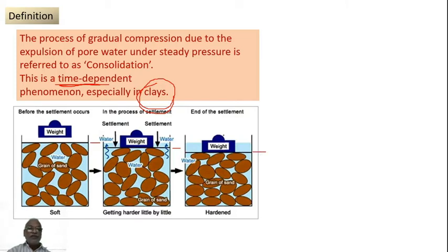So as long as there is some kind of pressure developed inside this pore water, it tries to go out, and then if that pressure is reduced to zero, there is no question of water going out. Now as you see here, when you put the load, there is pressure which is developed inside the water, it is trying to go out. By the time it comes up to this level, there is no pressure left inside the water. Because of that, there is no need of further expulsion of water.